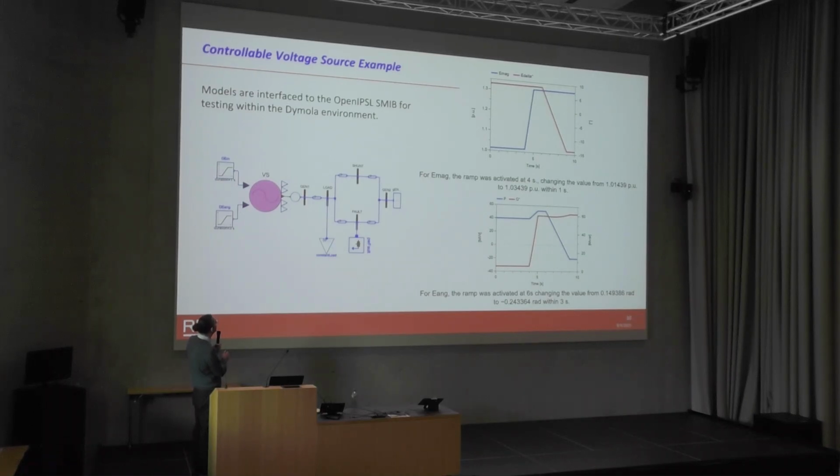And we just do a very, very silly thing, which is to do this large step on the voltage and this angle deviation and see if you can track. These things are extreme examples of variations that you could have, and if you can simulate it. So we run this in Dymola and then in the real-time simulator in ePHASORSIM, and we got the same answer, so we checked that the basic setup was fine.